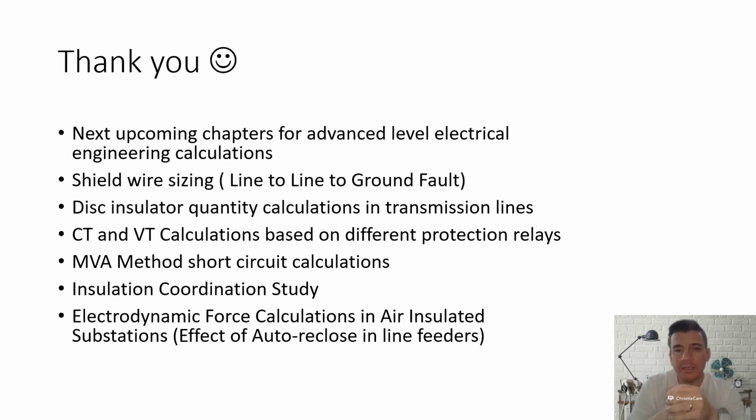Insulation coordination study. I think you know what I mean here. What is the required protection level of a surge protective device, a surge arrester? How are we defining its continuous operating voltage, rated voltage, and the energy dissipated inside of it?